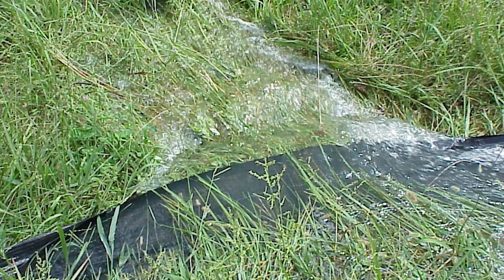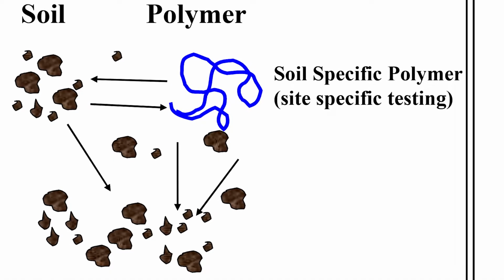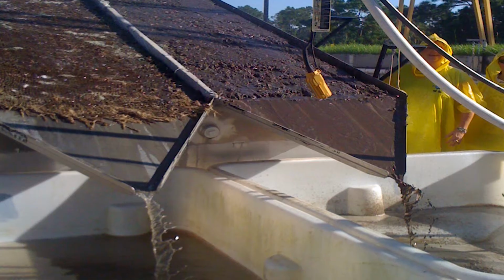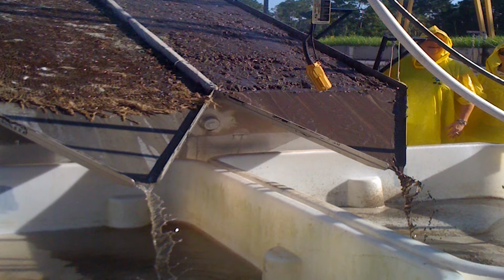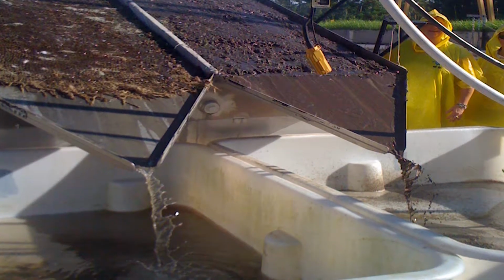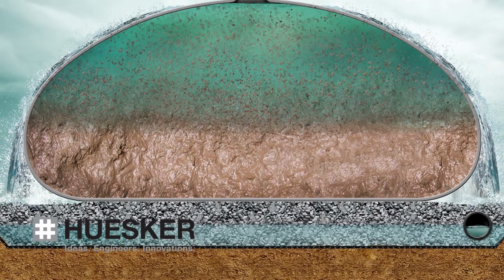How does it work? Flocculation is the process where a flocculant, such as a polymer, is used to reduce the turbidity of stormwater by binding particles at the soil surface or within the stormwater to form larger particles, flocs, that are heavy enough to stay in place, erosion control, or settle in the bottom of the stormwater and/or be captured within the construction site's perimeter.